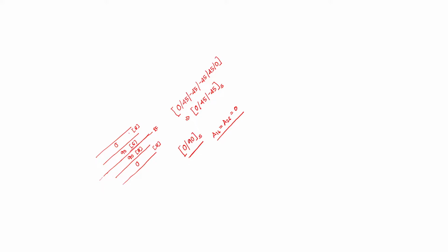It could be plus minus theta 1, plus minus theta 2, symmetric. Theta could be anything between 0 to 90. But when the layers are only 0 and 90, that's specially orthotropic. This is sometimes also called cross-ply symmetric laminate. Is that clear?